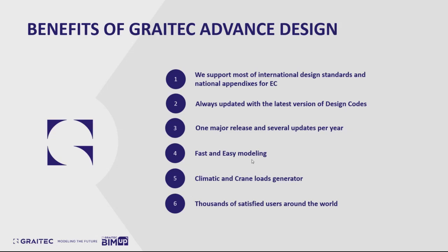For example, to draw a 2D frame or 3D frame, you have snap points automatically. You can actually add your members using those snap points. You don't need to define any nodes or coordinates, etc. We have climatic and crane loads generated automatically in Advanced Design.